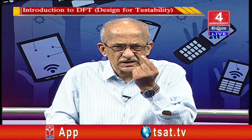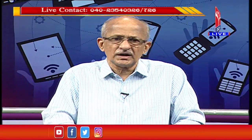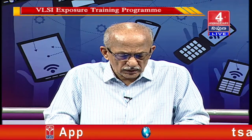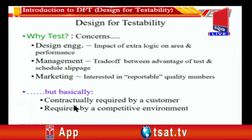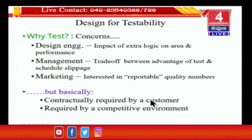So we have to see that no such nodes internally are stuck at 0 or stuck at 1. If there is even a single node which is stuck at 0 or stuck at 1, the chip is set aside, it is not sent for packaging. So these kind of tests are important, but basically it is required contractually, as a contract it is required to be provided to the manufacturer.